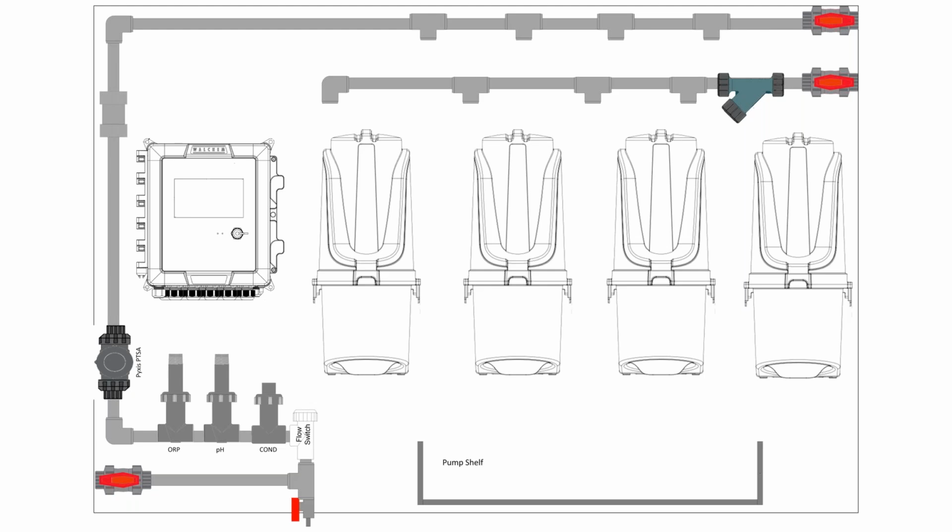Cool. Hey, and a quick sidebar on the PTSA. Whenever you're entering into a PTSA program, do not go immediately to the PTSA sensor controlling it as you transition in. You're better off running it on whatever your current method was, either by water meter or time, for a couple of 3 weeks, so that the chemistry transitions over.